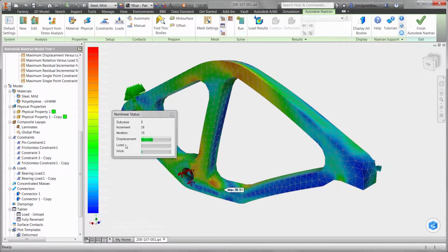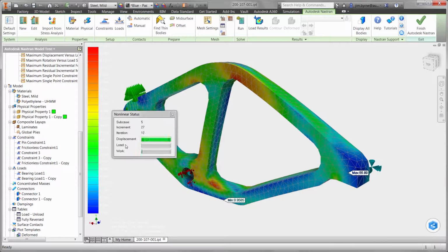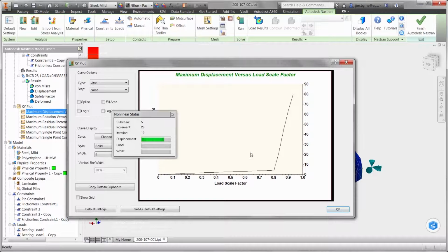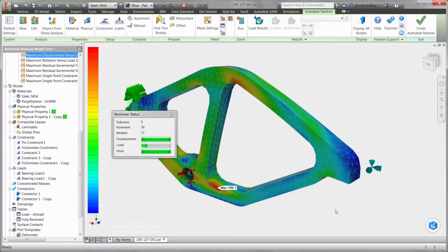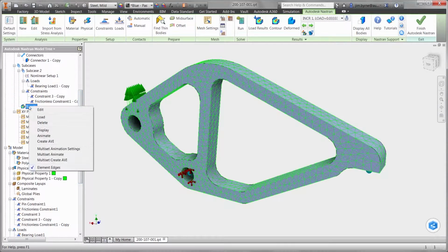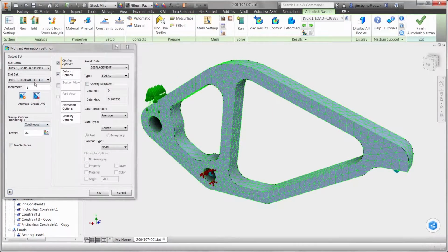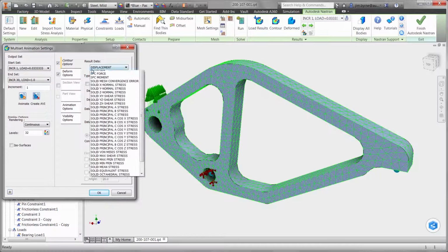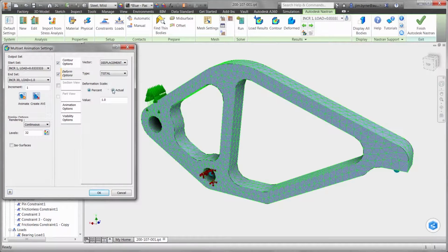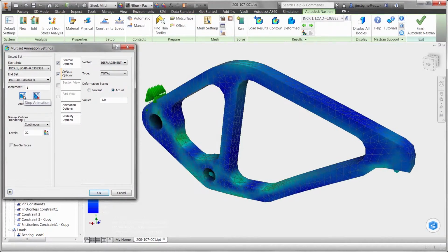They will only tell you if the material is going to pass or yield. Find out more about your design with fatigue, nonlinear, vibration, and thermal heat transfer. All within the CAD design environment. Even check the displacement of the model while the analysis is running. We can see that the part does in fact buckle at 1600 newtons. This does not satisfy our requirement of 2 times the normal load condition. Animations of the results may help to understand the weak points in the design for changes that need to be made in the model. We know that the design becomes unstable at 1600 newtons. By watching the animations, we can make better informed decisions for improvements to the stiffness of the geometry.